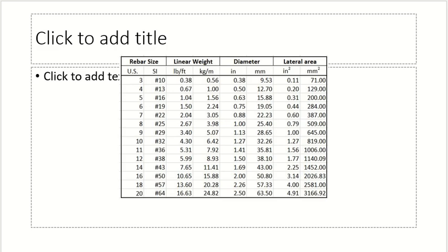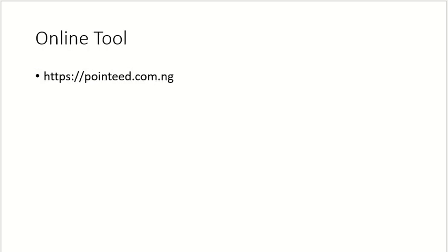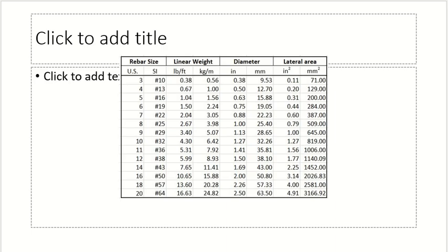Okay. And we did the calculation of how we can get the kilogram per meter of steel bar. We were using two things. What was that? How do I get kilogram per meter? What do I need? I need two items. Unit weight, okay, density, unit weight, and what? Cross-sectional area. Okay. So if you know the diameter, you can calculate cross-sectional area, multiply by the unit weight, you get the kilogram per meter, and they are given in different units.